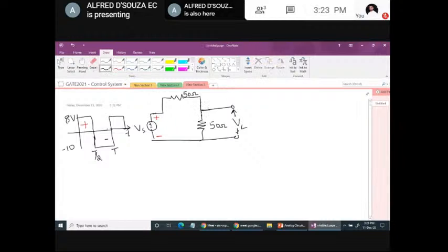And please observe what we have here is a potential divider network or voltage divider network. So we can have voltage divider networks like this as well. If you can apply the voltage divider rule properly, you can solve most of the analog circuits. So this is V, this is R1, this is R2. In a voltage divider network, we'll have one voltage source and two resistors, and voltage across the second resistor mostly we will take as the output.